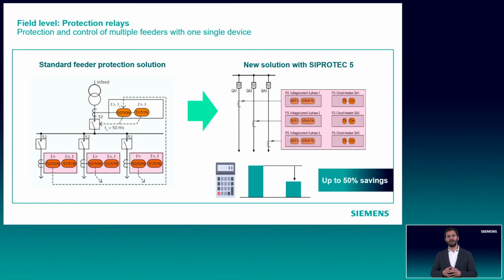Well, the next slide brings us a very interesting concept in cases where the plant runs with multiple medium voltage feeders supplying medium and low voltage loads. If we consider the traditional way of implementing a protection relay, normally we have one relay per feeder, and then the CTs, current transformers, and VTs, voltage transformers, from this feeder being wired to this protection relay.